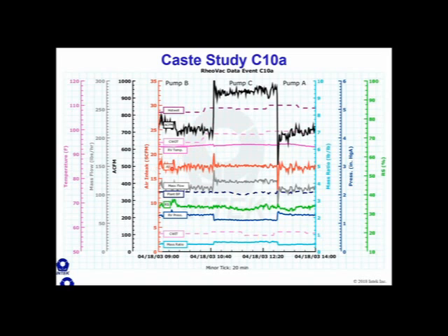Look at the air inleakage. The air inleakage is at about 17 SCFM. Not a really low value, but certainly not a high value, and certainly not one that would put your water to air mass ratio down at 0.5. I mean, that's a problem right there. They got pretty low back pressure. They're operating in the wintertime, but this is really low water to air mass ratio. They could reduce that pressure further. If they wanted to reduce condenser pressure, if there was a value to doing it, what should they do? They should operate all 3 pumps.